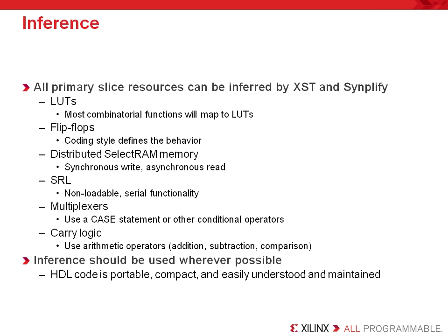A primitive is a resource that is written to the netlist that represents a LUT, a shift register LUT, a distributed RAM, a MUX. You get the idea. All primary SLICE resources can be inferred by XST as well as simplified. This includes LUTs, flip-flops, shift register LUTs, MUXes, and carry logic. However, you must be sure to code for the resources properly to get what you want. This means that if you define a flip-flop with an incompatible combination of control signals, you'll get something slightly different, probably with a LUT input used for a control signal.